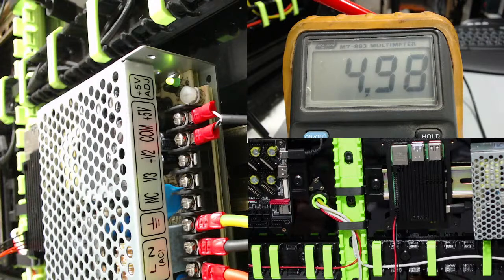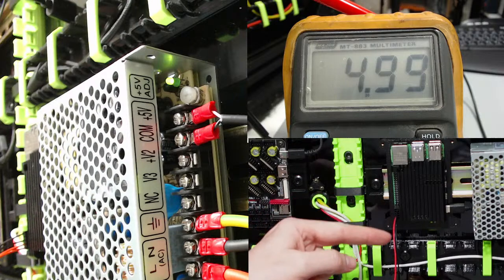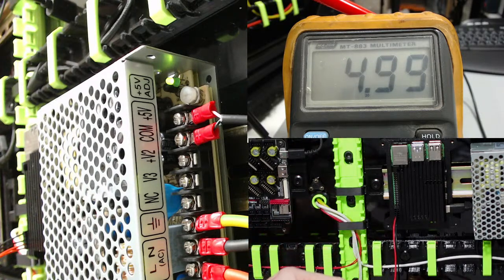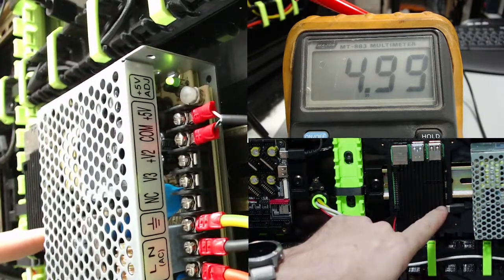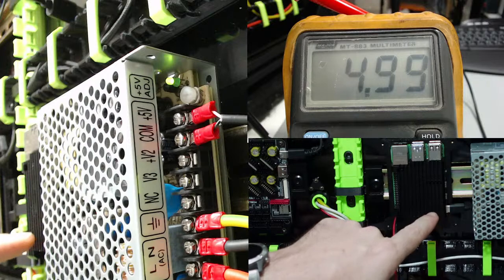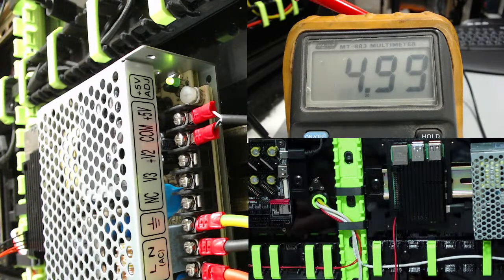So we're going to adjust this. Given that there will also be a bit of voltage loss over here, your voltage loss comes through your cable, and on the Pi itself, on the circuitry inside the board, there's a bit of a power loss. So we're really just trying to compensate a little bit for that power loss. Now, I want to have my voltage at 5.1 minimum. For safety's sake, I'm going to go up to 5.15.